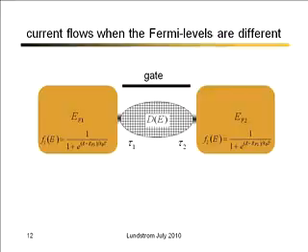Okay? And then we think about having two contacts which are always large, there's a lot of scattering, they're maintained near thermodynamic equilibrium. Any current that flows is just a small perturbation and doesn't really disturb equilibrium in these two contacts. Each one is characterized by a Fermi level or electrochemical potential. It's just that we might have different Fermi levels. If we apply a voltage to the drain, we lower the electrochemical potential in the drain. So the second Fermi level is different from the first. But they're equilibrium Fermi levels.